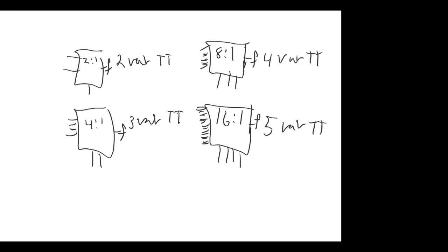So now that's as far up as I go. The 74150, that would be your 16-to-1. The 74151, that would be your 8-to-1. The 74157, that would be your 2-to-1. And the 74153, that would be your 4-to-1.